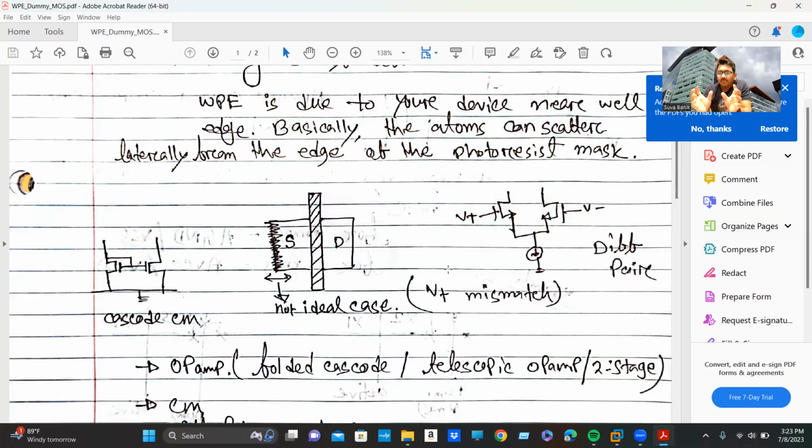And for crucial analog circuitry, I'm giving some examples, let's say a differential pair, which I'm making a video on right now, and I also show how to match this differential pair. For this differential pair, there are two transistors, and if there is any threshold voltage mismatch, then what the designer expected in their pre-layout simulation, they definitely will not get a similar response after post layout.